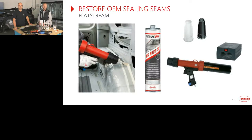So, well done, the flat and wide stream application. I hope you have enjoyed it. The last application you have seen is a special application when you have the sill on a car body. For example, the Caddy has a long sill and they have this wide, wavy texture on the side. With this line application, you can do this in one step. One cartridge each side, job is done. Quite easy. You don't have to sit here and brush it like before.